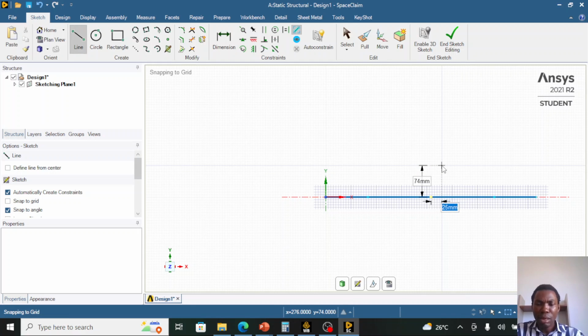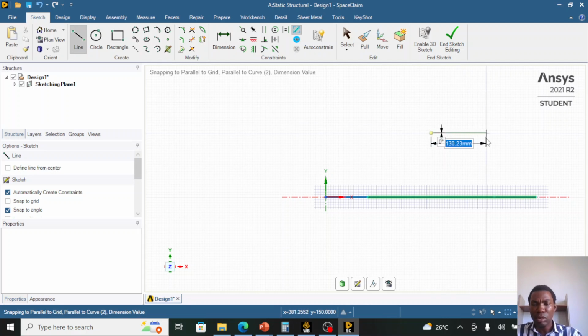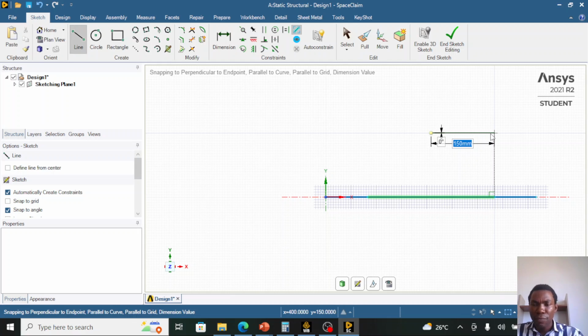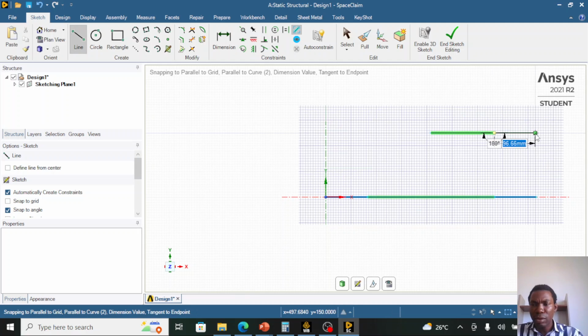Enter 0 as your x coordinate. Tab to move to a y coordinate. Enter say 150. So this defines the beginning of my node point, which is directly above the center point of our full model sketch. So the length of this first part is 150 mm. I have that. It's already defined as 150 mm. The length of the second part is 100 mm.